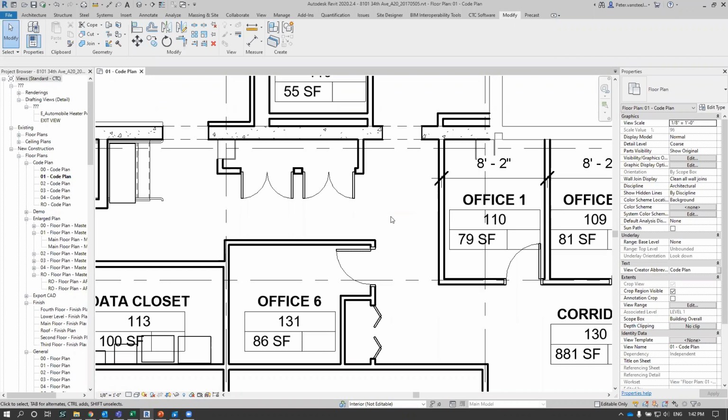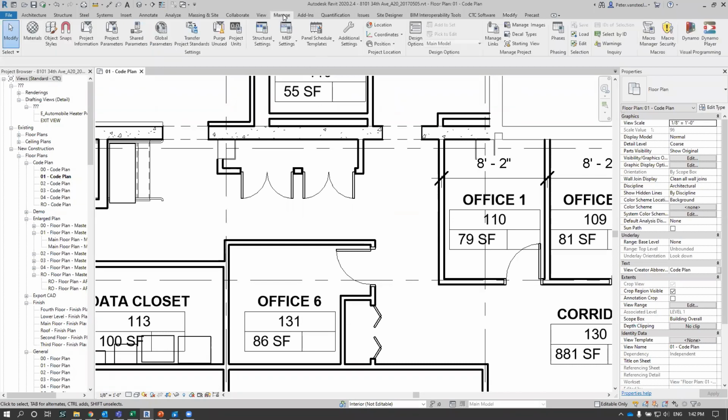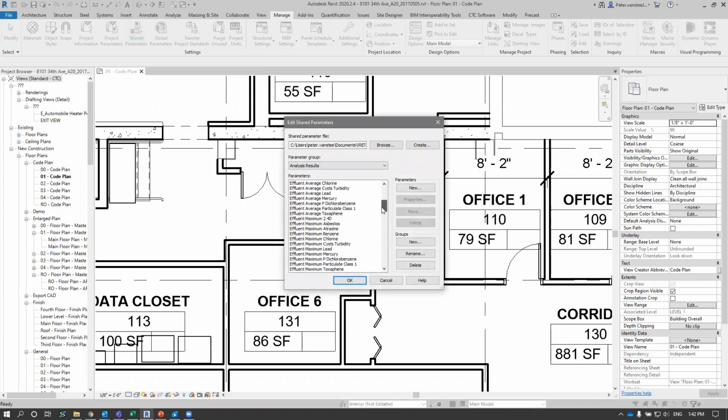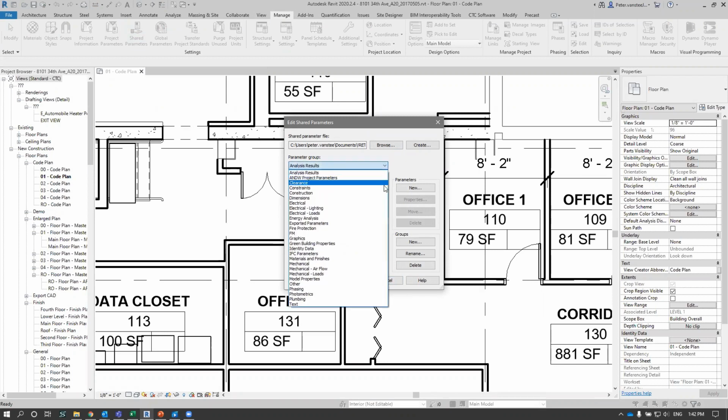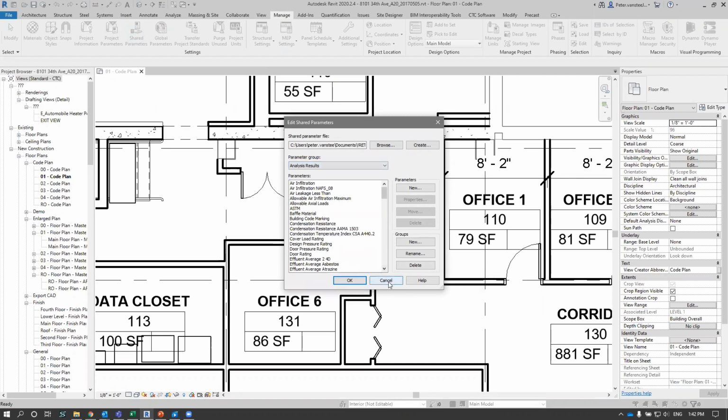But to start off, everything in the entire project is really based around our shared parameters. So our shared parameters that we need to work with are entirely based on, let's say, we all kind of see that if we go to Manage, we can see our shared parameters, and we can actually see a whole list of all of the shared parameters that we have. Now, these are the basic ones. This is my shared parameter file that I'm using currently. And it has a lot of different stuff in it, and I have a lot of different groups and stuff built into that, and that's fine.